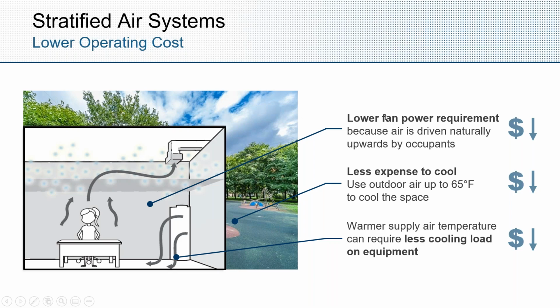And then operating costs. As you would probably imagine, unlike the ceiling supply system trying to push the cool air down to the lower level, this delivers into the space and lets natural convection drive the air throughout the space. So the static pressure is around 0.05 inches water column or less across these diffusers, which can really help, at least from the terminal device's point of view, lower some of that system static pressure and ultimately result in lower fan horsepower required by these systems.